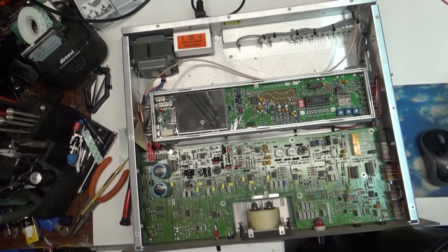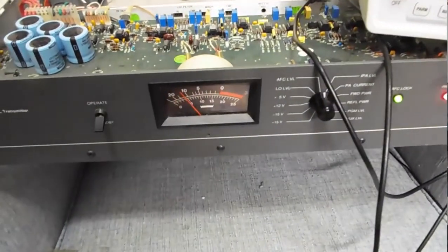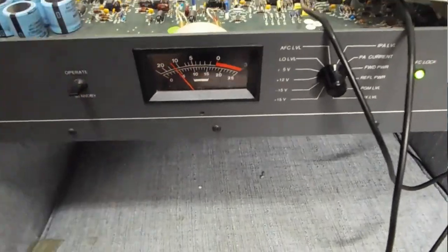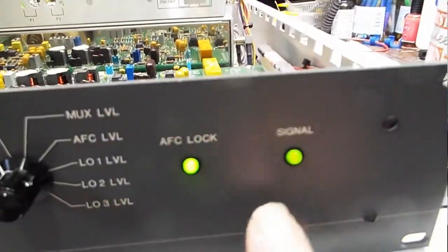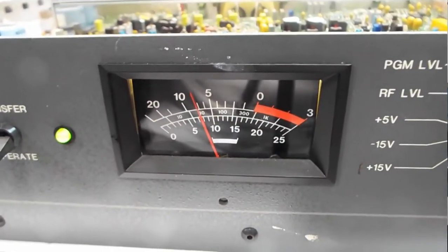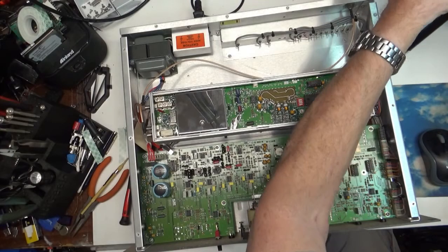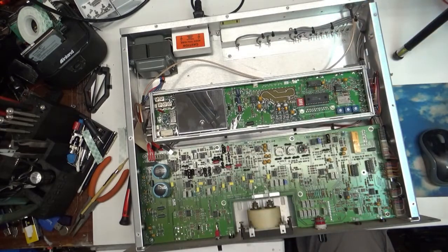In back of me, I've got this guy set up. The transmitter is set up with 2 inputs. I've got the 26 kilohertz mux and audio. I'm going to turn it on. It's transmitting on our frequency. And I'm going to come back over here and look. The green light is on, and our RF level is high enough to get past the squelch. Cool. Turn that off real quick. Oh, batteries don't last very long.